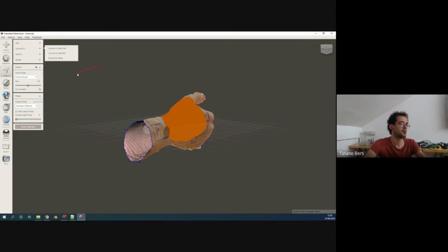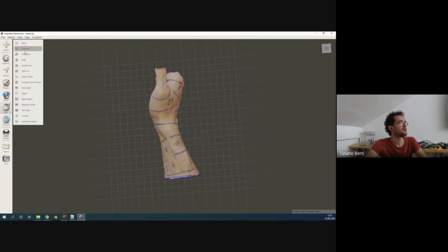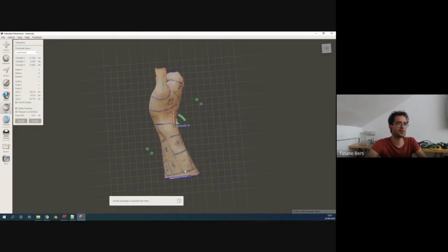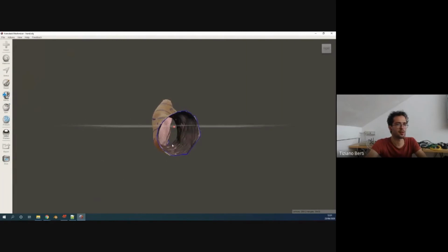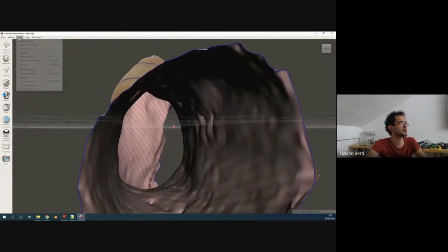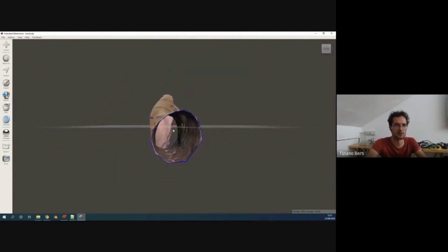So the basic step we are doing here, the first thing we check is that our mesh is placed correctly compared to our planes. I usually do that by looking at this red point that you can see when you have show grid activated on view. It's the origin of the file. So the origin is already at the center because I put it there in Zephyr 3D.